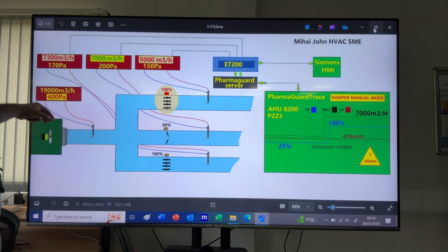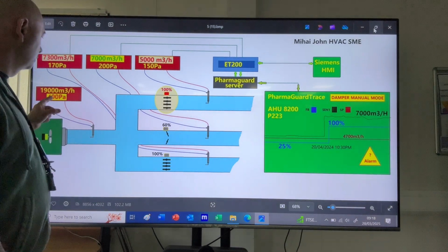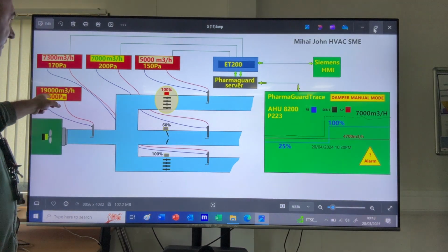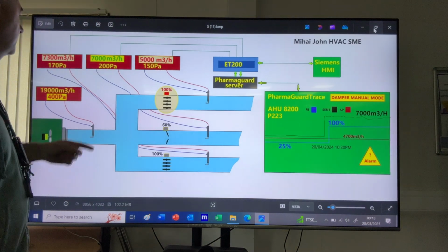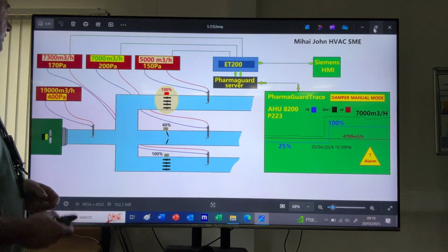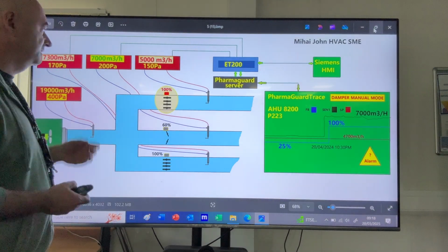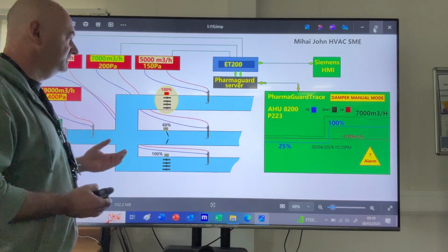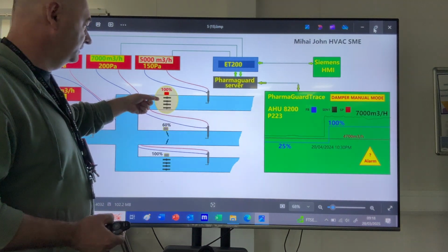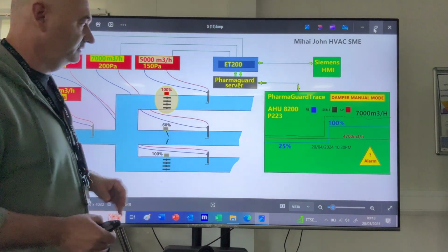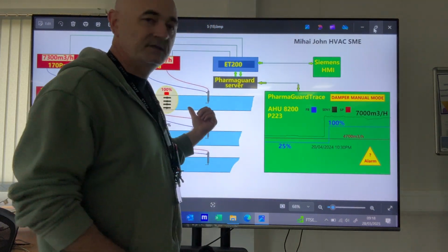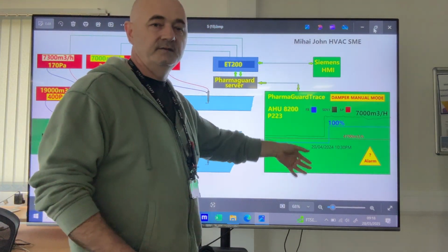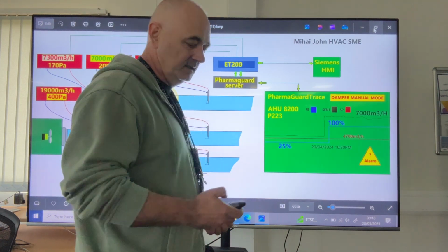The entire system is compromised because look, the pressure dropped. The global airflow looks for the quantity, but the pressure dropped. When the pressure dropped, the other dampers also lost airflow because they are set up to be on manual mode. They cannot compensate. So if someone acts on one damper, the other ones cannot compensate. They remain fixed. But I can capture the time when this damper position has been changed. Then I can question why it's been done like this, or who, we can investigate this.